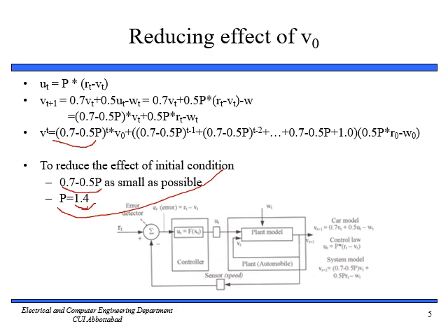In this condition, this lies between minus 0.6 and 3.4, because at minus 0.6 we were getting oscillation, and at 3.4 the rate of decay was too fast. So we have the best possible condition, that is 1.4. So let's move on to the next slide.